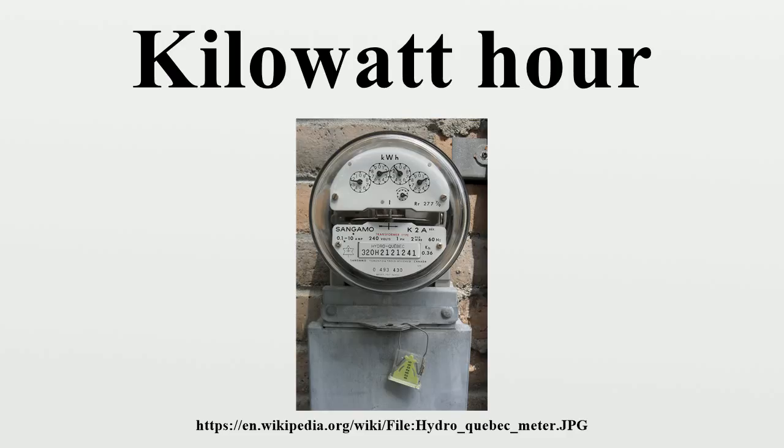Examples: an electric heater rated at 1000 watts, operating for 1 hour uses 1 kilowatt-hour of energy. A television rated at 100 watts operating for 10 hours continuously uses 1 kilowatt-hour. A 40-watt light bulb operating continuously for 25 hours uses 1 kilowatt-hour. Electrical energy is sold in kilowatt-hours.